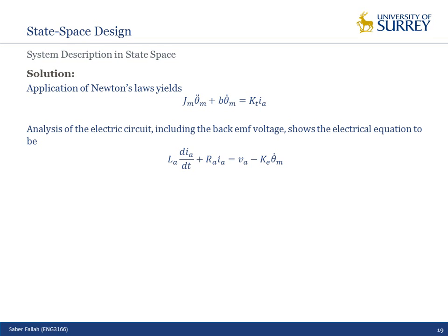To convert these differential equations, look, I have a second order differential equation, and I have one first order differential equation. How many states do I need at least? I have a second order differential equation, so I need two. Yes, exactly. I have two states to represent this second order differential equation in the state space format. And here I have the first order differential equation, so I need one state to represent it. So in total, I need 3 states.